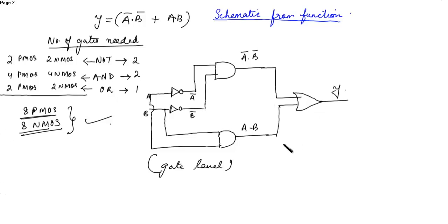So first, draw the schematic by using this function. First, the inverter. So this is the inverter. First inverter, now this is the NMOS.